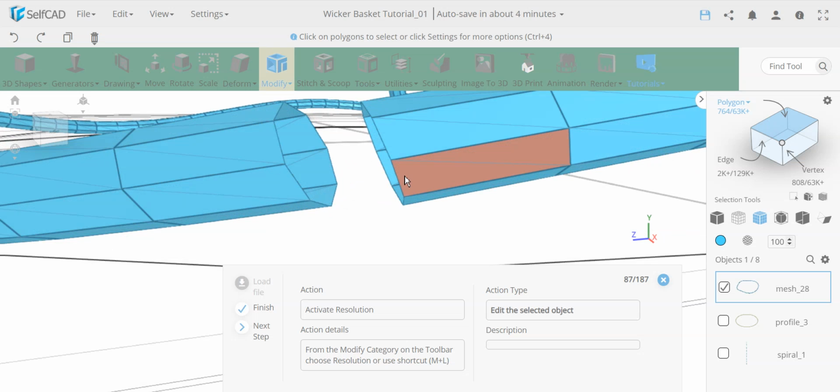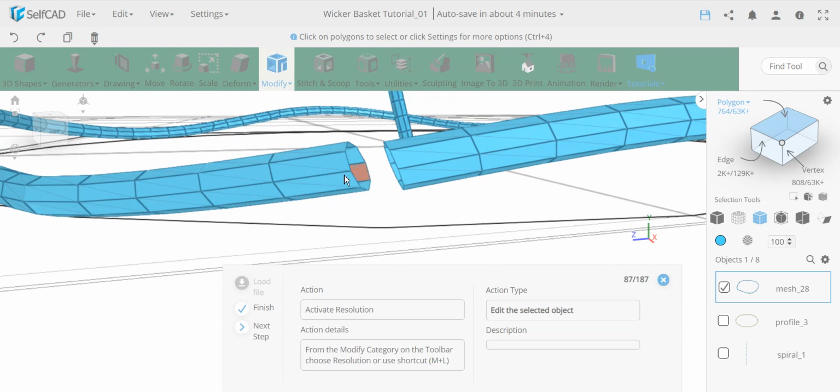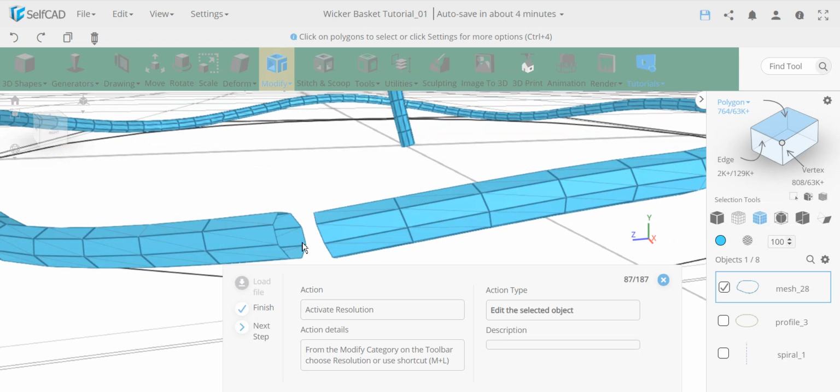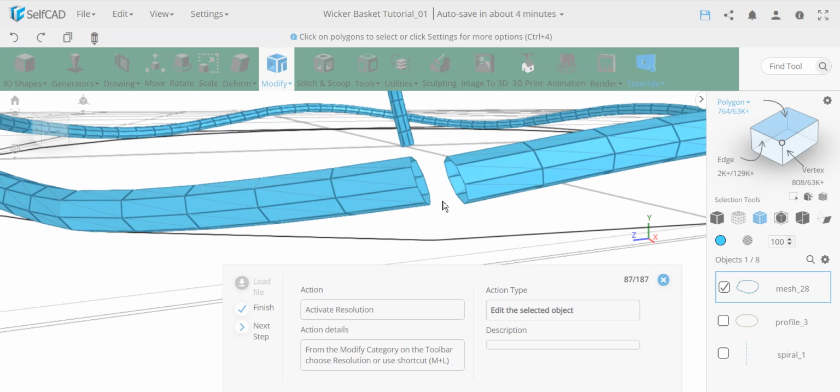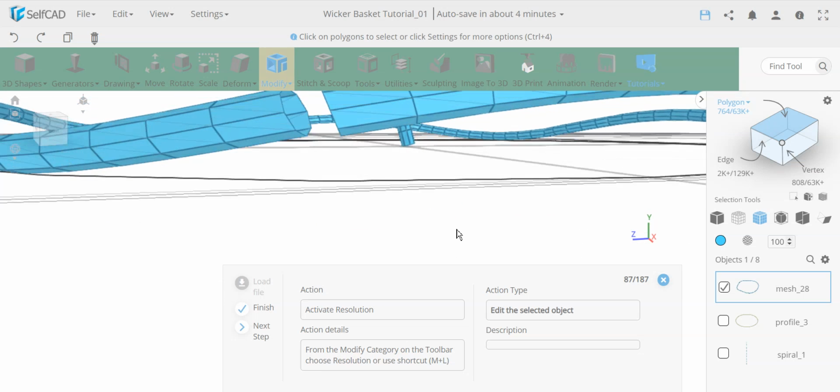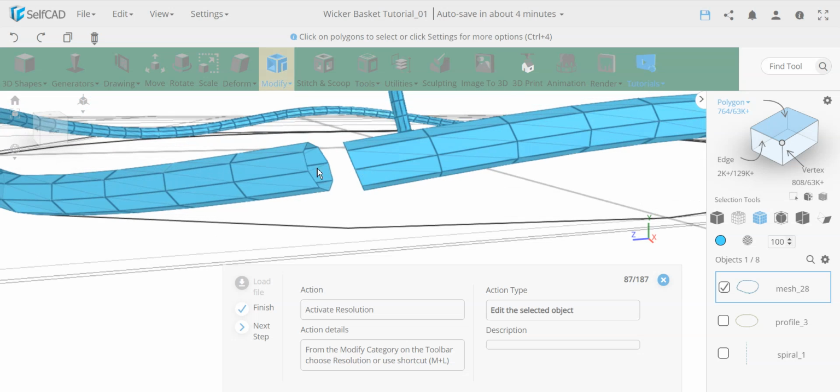But when you bridge this, there's actually three things that need to happen when you close something like this. First of all, there's something that is called interfaces, and this is what we manually deleted. There are some tools that can delete them, but it's always better to manually delete them if you know how to do it. The second thing is we need to create this section. There's a few ways we can do it. We can stitch them together using a few tools like edit details, or other tools. Or you can use a tool that is going to build in the missing piece over here automatically. And then once you add the missing piece, we need to make sure they actually connect perfectly.